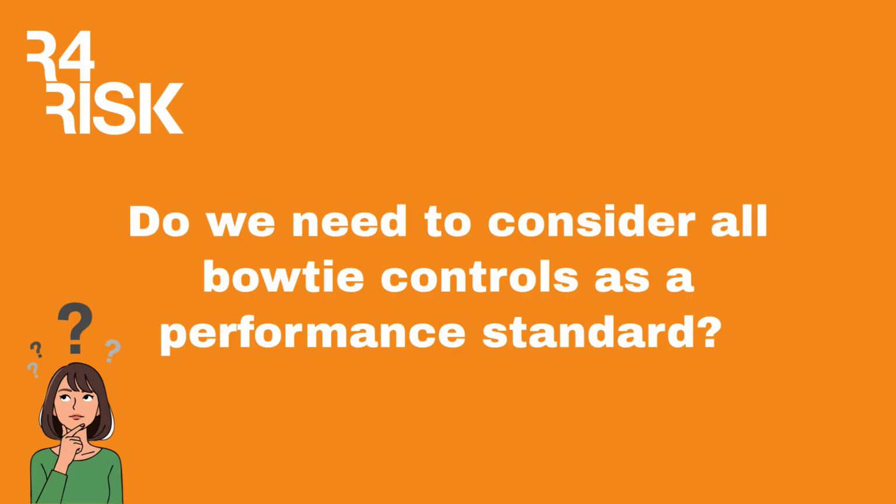And here are my standards for maybe my pressure relief devices. So you don't need to go to the nth degree to define standards for a bursting disc versus a pressure safety valve and stuff like that.